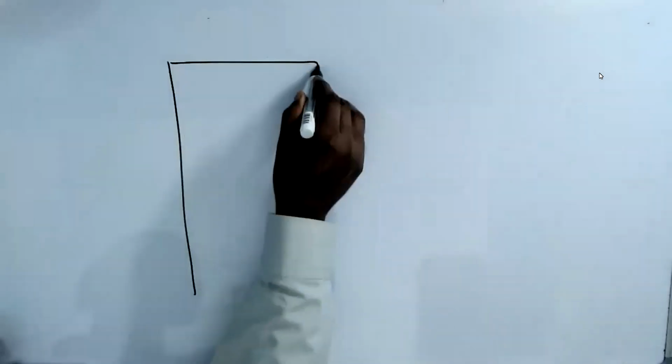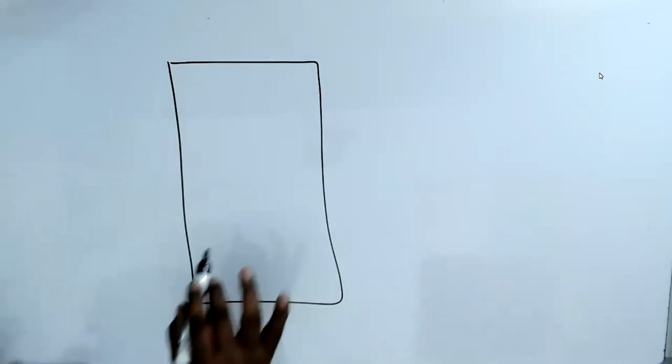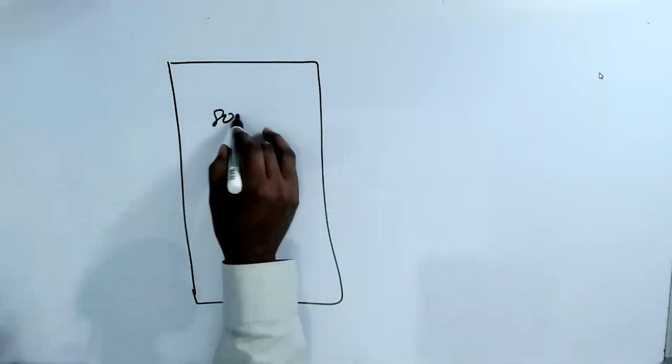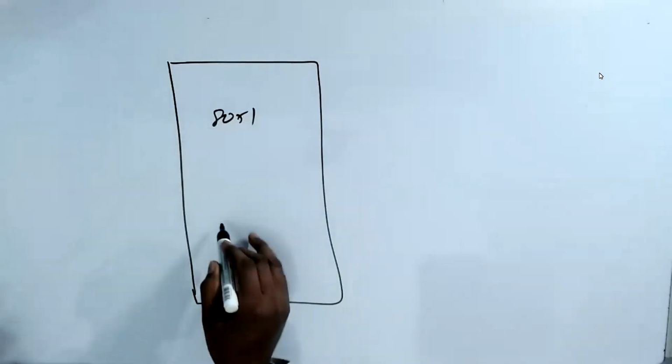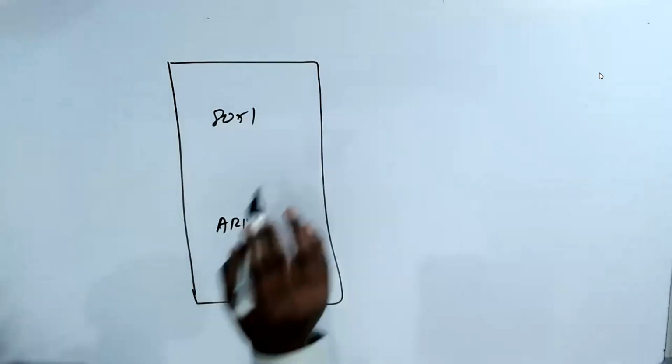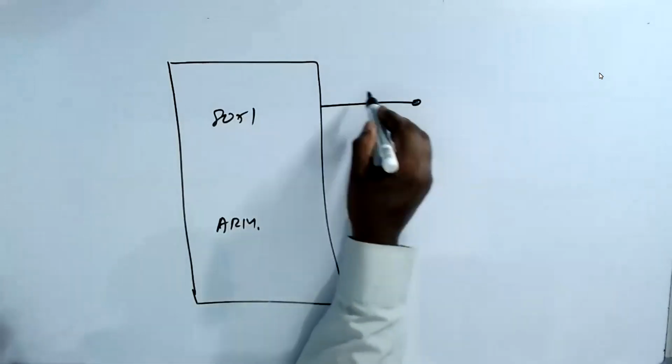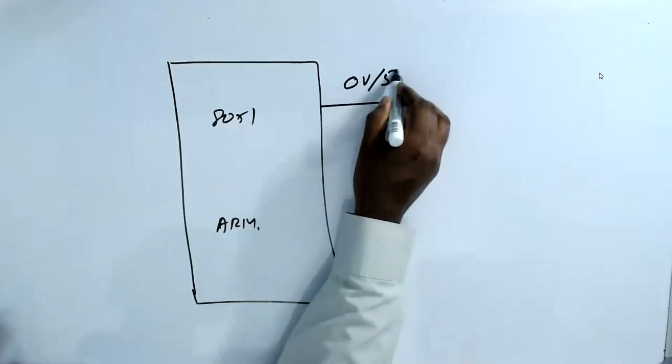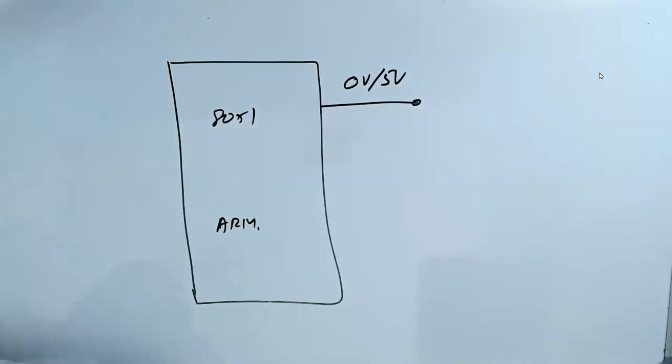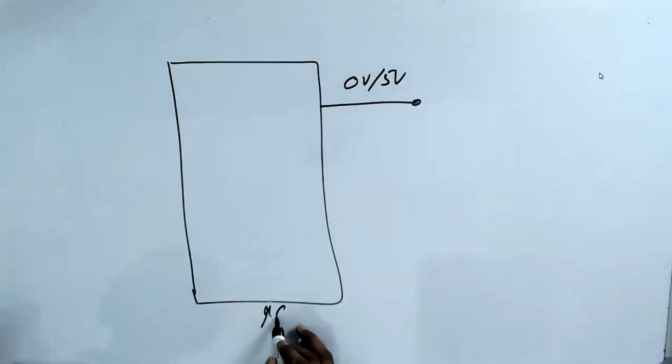If you notice, in all these things we are discussing, you have a microcontroller, and it doesn't matter what it is. The microcontroller can be an 8051 or the latest ARM. You control a pin, that's all. You can make the pin 0 volt or 5 volt. That is what is possible. So our programs are common for all the microcontrollers, not specific.